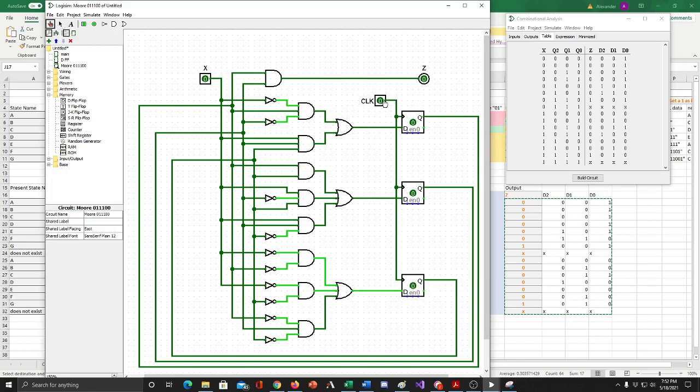And so if I hand it the code it's interested in, which was 0, 1, 1, 1, 0, 0, it outputs a 1. If you input anything else in order, it will not go to 1, and it should be keeping track. So that's the Moore machine. You would do Karnaugh maps for this in general, but we let Logisim do it for us. And now I'm going to cut this video here, and we'll switch to the Mealy machine. There's going to be only a couple differences, but I will cut to that right now.